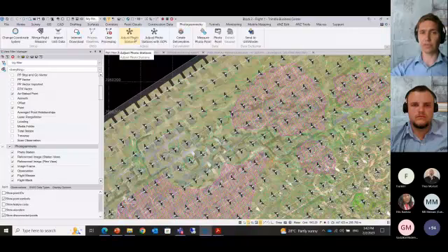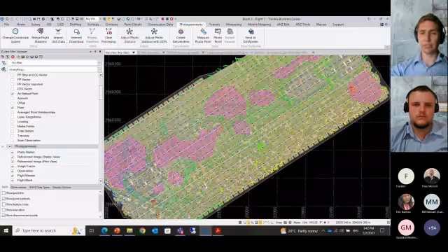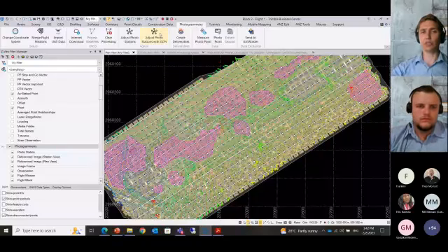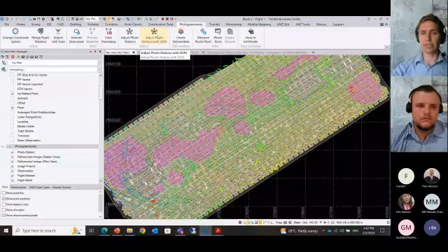So you'll start with the adjust photo stations. In this process, it basically looks for tie points from all the various overlaps between your photos, looking for common points. And then the next step is to do your ground control points, where you would now go in and actually snap to those ground control points.